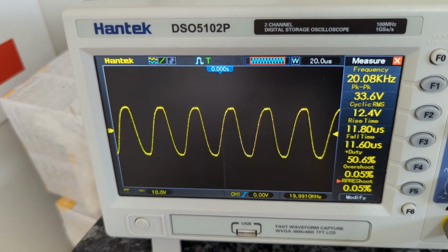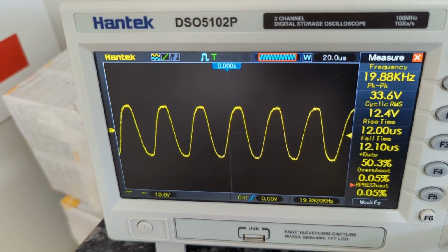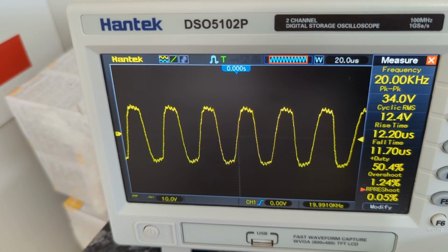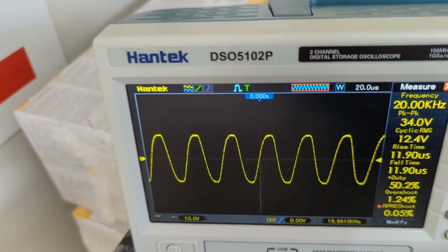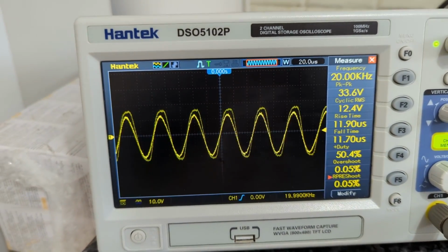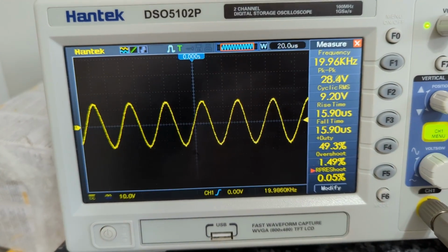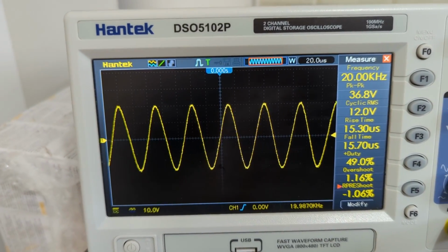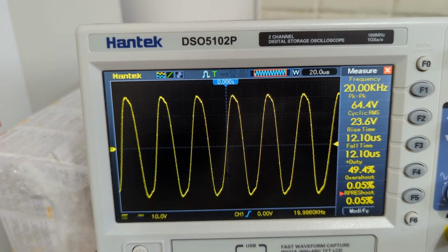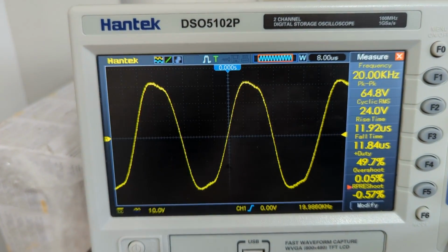So you see that RC filter, it kind of removes that, but not fully, and by doing that it kind of rounds off the edges even more. So actually, just for fun, we can try to measure this square wave. So sine wave looks already cleaner. This is a 20 kilohertz sine wave. Let's see where it clips. There we go. This digital clipping looks a bit different than a B-class clipping.